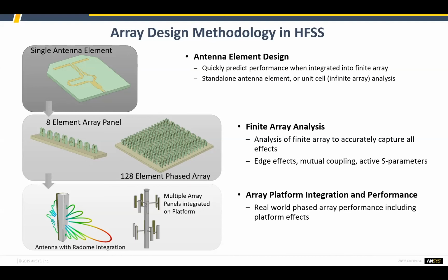And then of course, once we have a solution to the array, we can simply integrate it with a radome, or we can place the array on a superstructure, whether it's in this case as shown a cell phone communication tower or the side of a battle cruiser. We can then take the HFSS array model, make it a source, and then we can use the SBR solver to help us figure out how this array will work in the real world when it's deployed.